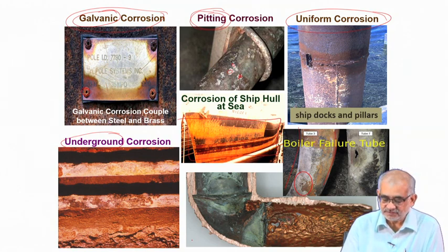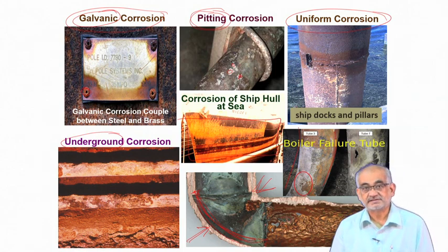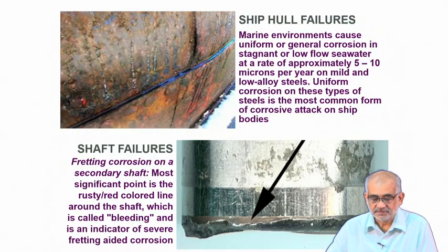But if you think of this kind of bent tube, then obviously the amount of stress experienced at the top bend will be lower compared to the amount of stress experienced along the bottom rim. So obviously you expect a lot more damage occurring here. The effect of stress along with the high pressure of the steam and its oxidative action will be higher here. So we tend to see a lot of damage happening here.